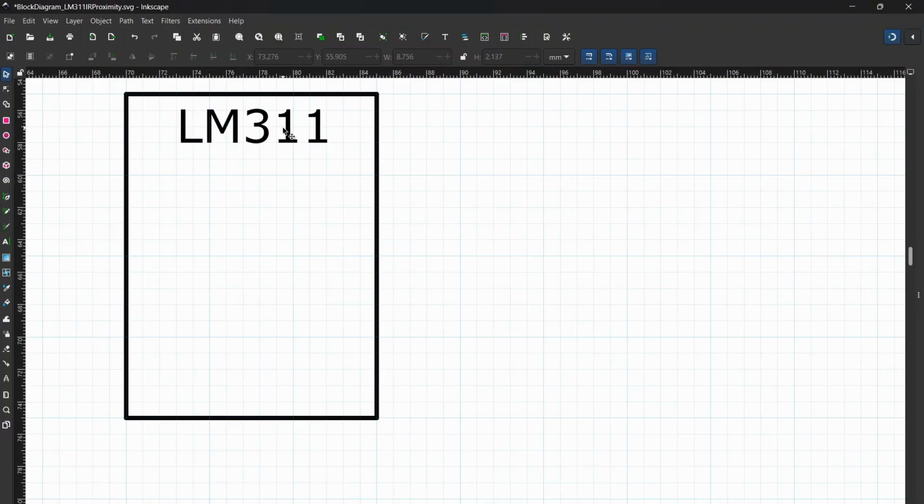8 numbers. But if it is a larger scale IC or a microcontroller such as the ATmega328P or a PIC microcontroller, just indicate the pins that you are using for the circuit. Do not include any unnecessary pins.